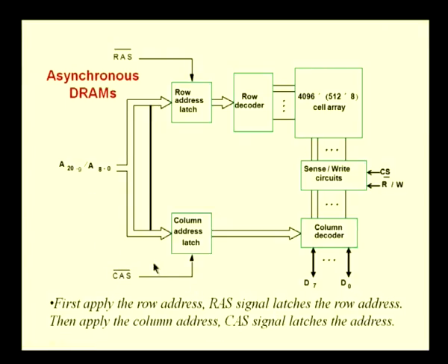Let us look at what we do there. The way we use this is that we will first select a row. The addresses themselves will come in two parts: we will first send the row address and then use the same address lines to send the column address. So, you can see that we are multiplexing the address lines.